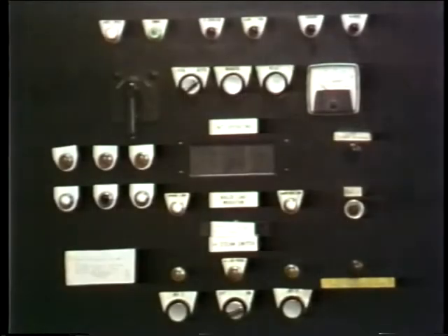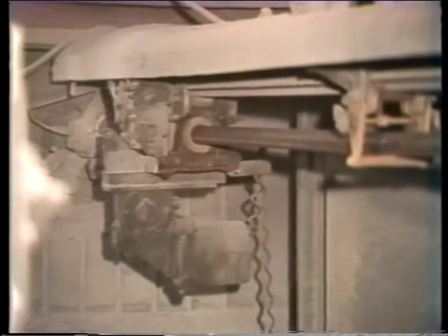First, proper cycling of a soot blower is necessary to provide for a complete cleaning job. Also, if a soot blower doesn't follow the proper blowing cycle, it can damage the boiler by causing erosion of the tubes. Failure to cycle properly can interrupt the sequence of the operation of the entire soot blower system. Things that can cause improper or incomplete cycling of a soot blower include improper adjustment of the drive and valve actuating mechanism, failure of drive power, and failure of parts in the drive mechanism.